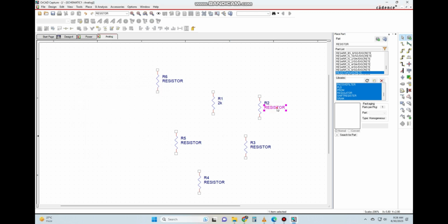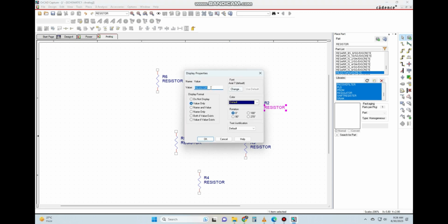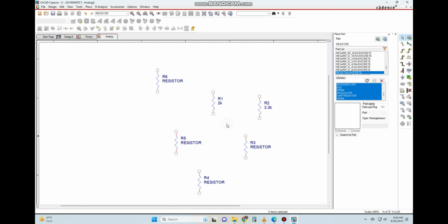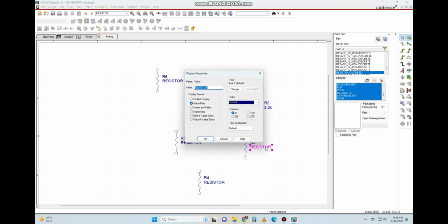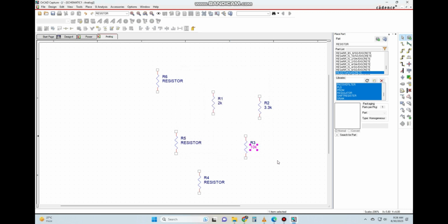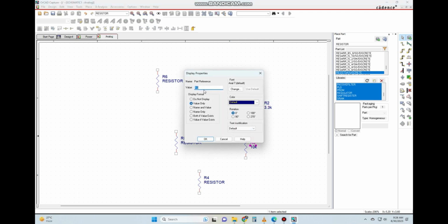Let's say I'm writing 2K, 3.3K. I can also change the reference designator of any component as per my convenience.